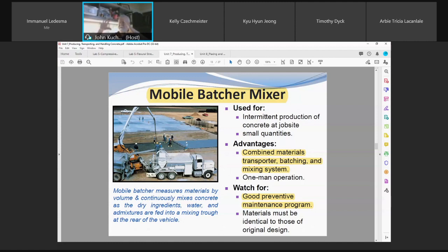You got to remember, if you look into a revolving drum mixer, there's fins or baffles, and that gives you the shearing of the concrete. Well, sometimes those old mixers could be 15, 20, 25 years old. Those fins inside eventually wear down, so they don't give you a good shearing action. That's why with transit mix, you can have inconsistent loads because every truck is different.